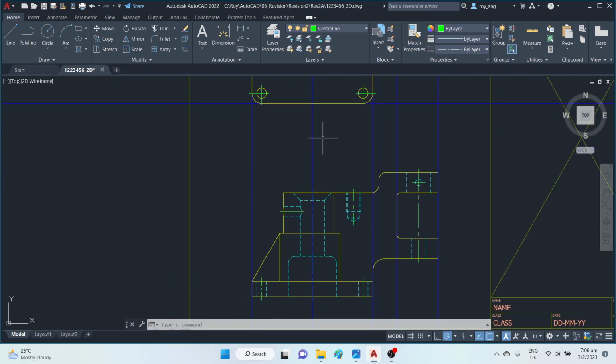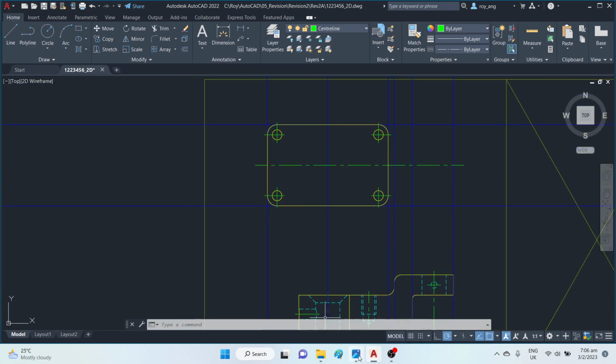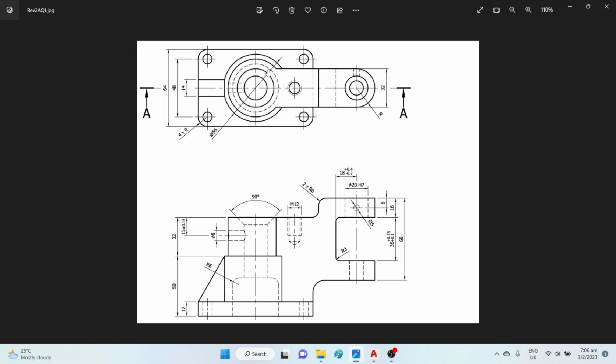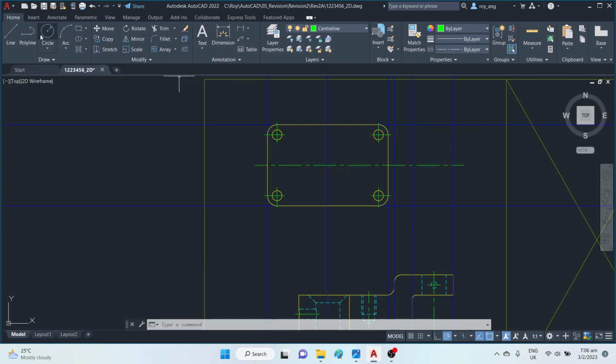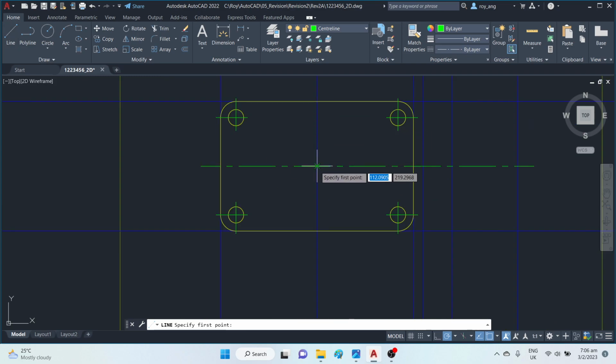The next thing I'm going to draw is, my approach is to draw the base, draw the outer cylinder, the rib, the inner rings, and then after that the extension, the features here, and then the extension, the features from left to right. So I'm approaching from left to right, right? So once that's done, since I'm in the center line, I might as well do my center line here. And the center line is for the circle. It doesn't go past the outline of the base because it's not symmetrical about the y-axis, it's symmetrical about the x-axis.